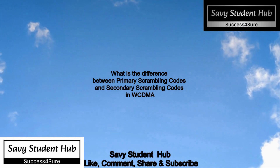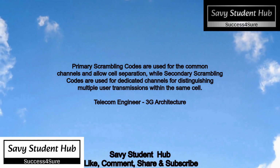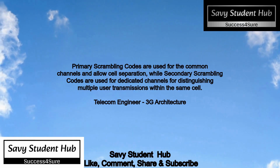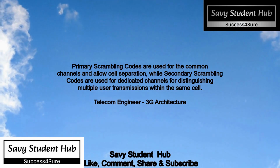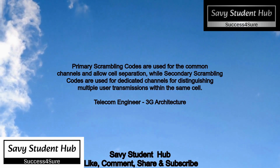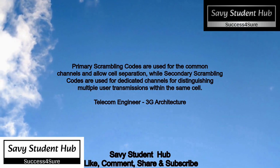Primary scrambling codes are used for the common channels and allow cell separation, while secondary scrambling codes are used for dedicated channels for distinguishing multiple user transmissions within the same cell.